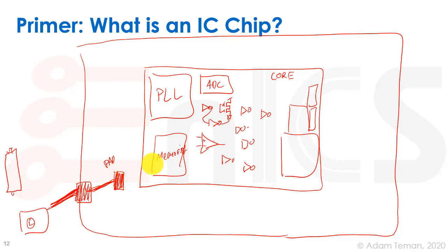Okay, and we have to have that pad interface with the rest of the chip. And for example, if we want to drive a signal from the chip outside, what we need is some sort of a buffer, some sort of an inverter, but not a small one that fills up this little tiny capacitor, but rather something that is able to fill up these huge capacitors that are many orders of magnitude larger. So we're going to put this buffer or inverter or something like that that's really big. It's many thousands of these little transistors and gates that are connected in parallel, and we're going to make a little block like that that's going to be on the chip, and we're going to call this an I/O.